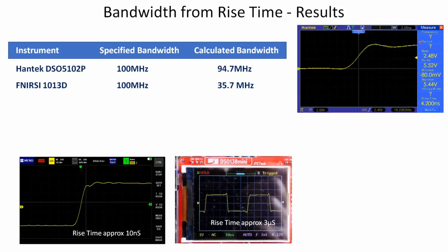So it's quite difficult to measure the rise time, because the fastest time base is at 10 microseconds per division, and I've sat for a bit and decided that I reckon the rise time is about 3 microseconds. So putting those numbers into the calculation gives us about 116 kilohertz as a calculated bandwidth, and the specified bandwidth is about 200 kilohertz. And I wouldn't argue too much with that, because you could probably say that my estimation of 3 microseconds isn't very sound. So I think 116 kilohertz is probably being a little bit unkind to it.